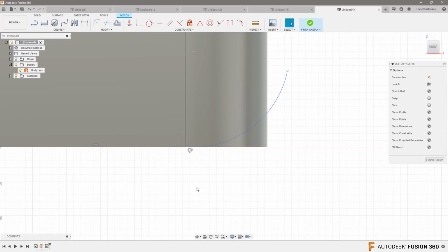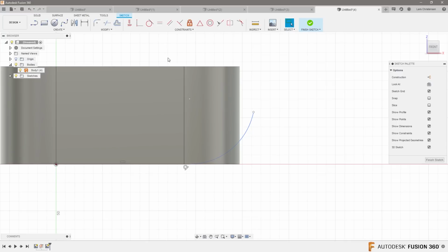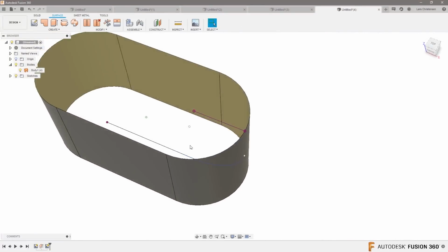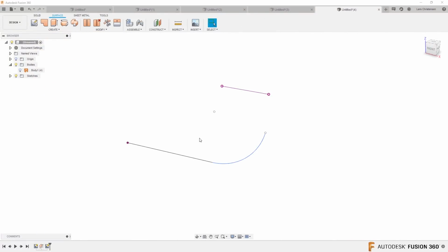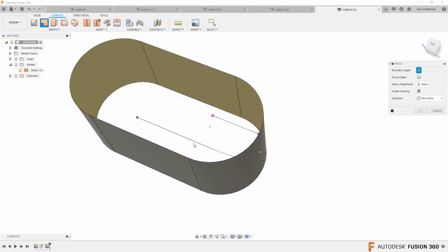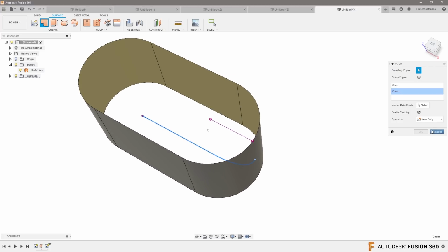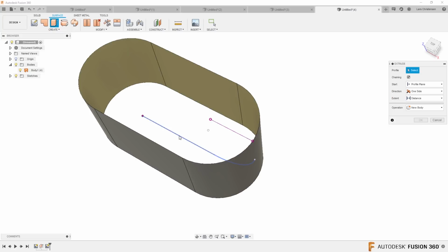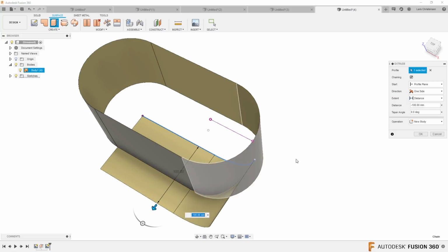Now, what I could be tempted to do is to say, all right, let me press P for project and select this so I get the end point here. And let's make these two vertical, right? I'm still leaving some things underdefined. But really what we have right now, if I finish this, is that we have created this shape. If we then extrude that out, so we're making 2 different extrusions. So let's select this. Extrude that out. And let's just go one side.